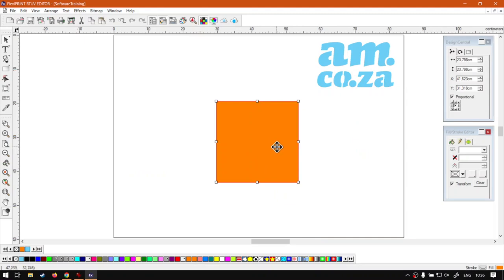So that's pretty straightforward. Another way we can constrain this shape with our freehand move is to use shift. Now if I use shift, you can see I can constrain it on the horizontal. It's just easier. My mouse moves and the shape stays there, and only at a certain point will it snap. Then we'll do it on 45 or the vertical as well.